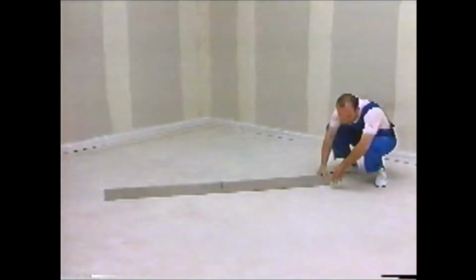The subfloor shall be clean, free of paint, plaster, or slurry deposits. It shall be solid and cohesive in depth and at the surface. Cohesion will be measured using a Schmidt hammer and shall have a compressive strength of 15 megapascals. It shall be flat with variations no greater than 5 millimeters over a distance of 2 meters and none greater than 2 millimeters over a distance of 20 centimeters.